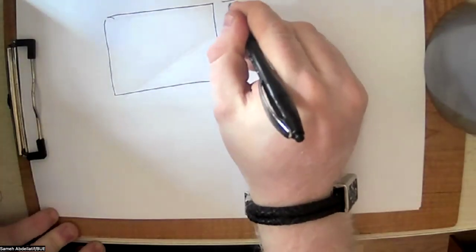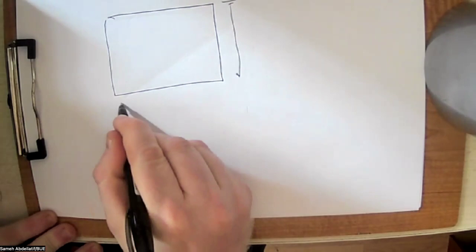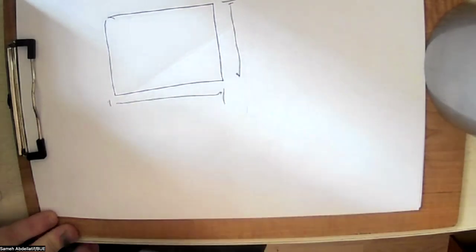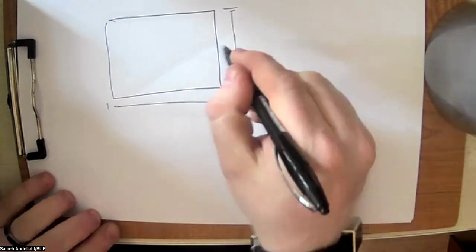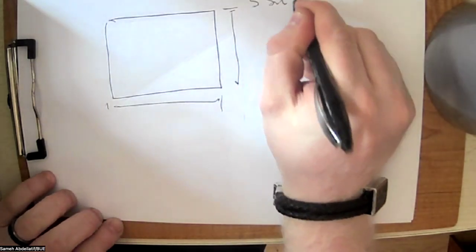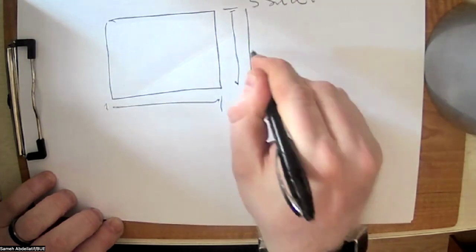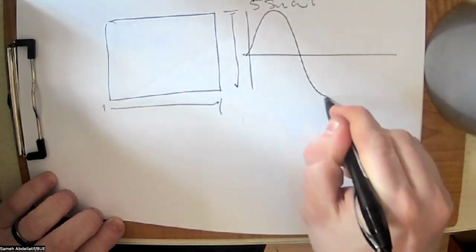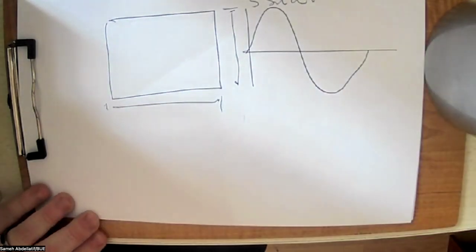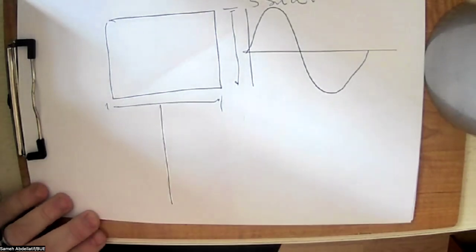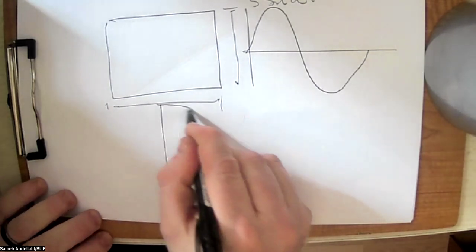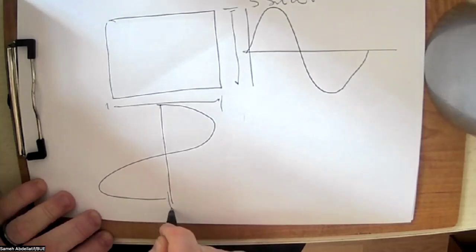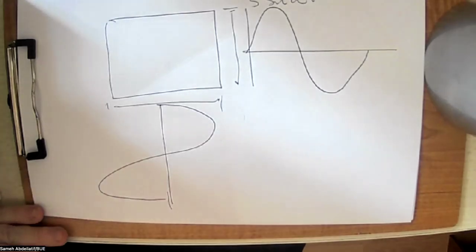Here is the vertical variation, and here is the horizontal variation. So in the vertical variation, I'm going to insert, for example, 5 sine omega t. And in the vertical variation, again, if you remember in the previous part, we already did the same, but we inserted a trigger here. Now I am not going to insert a trigger. I will also insert 5 sine omega t. And again, this is a 90-degree shifted representation.